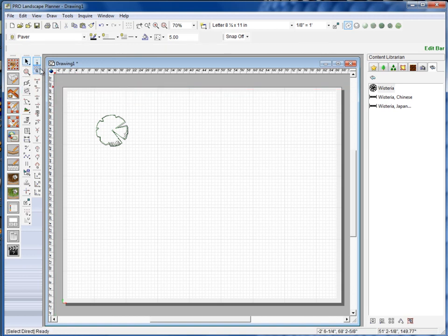The next toolbar is the Snap toolbar, which we'll get into the Snap tools. Snap tools work in conjunction with other drawing tools. Okay, down here at the bottom we have our status bar, which gives us an instruction or the current state of the program. And on the far right corner we have the absolute and relative grid coordinates where we're currently positioned on the grid.